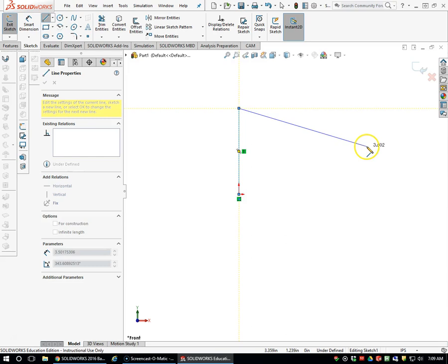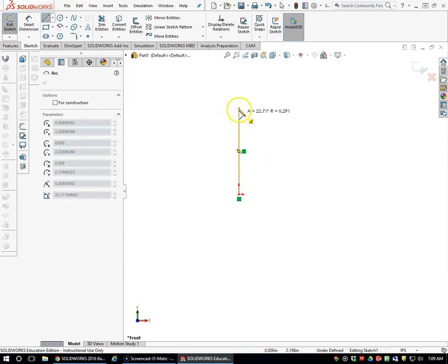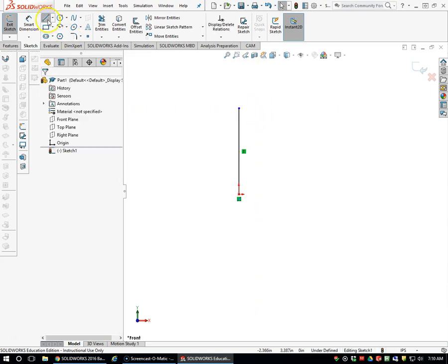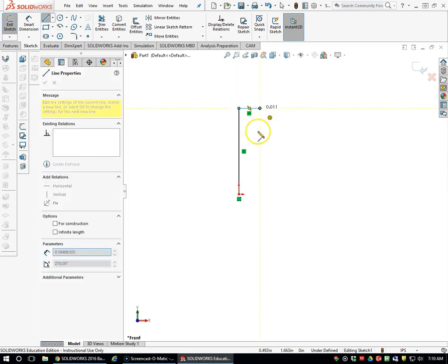We're going to try to create the sketch that the author has illustrated. As I draw this sketch, notice I've got like a rubber band. Whoops, if I go back there, I'm getting a straight line again. Got a rubber band attached to my last point. If you've lost that, you can just click on that last point and start again. I'm going to click. Oops, I did lose it. Grab the line. I just hit the escape button. Click right back on the end of the line and begin again.